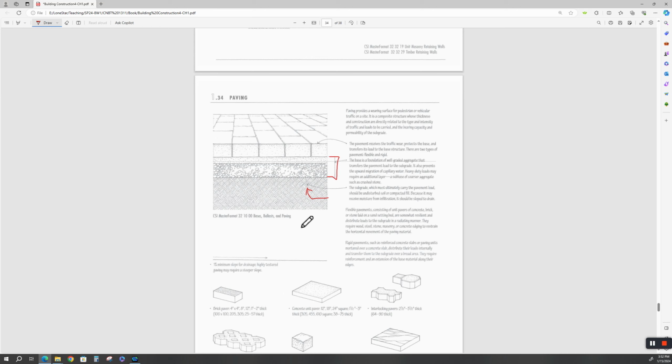In the super heat, like this last summer where we had three months of triple digits, some of the concrete pavement popped at the construction joints and expansion joints. So you could spend a whole lifetime becoming a subject matter expert on flexible pavements.